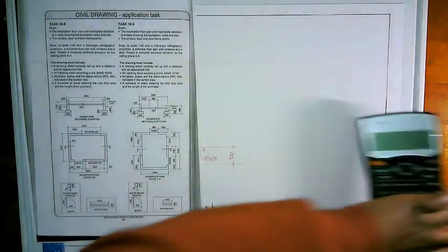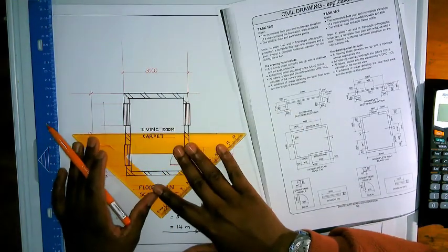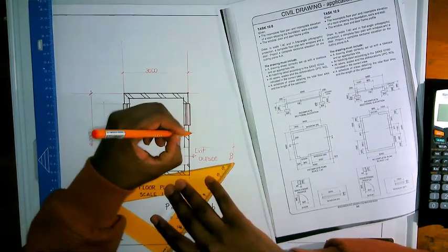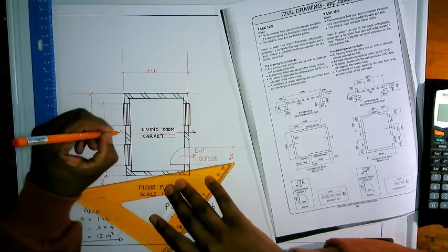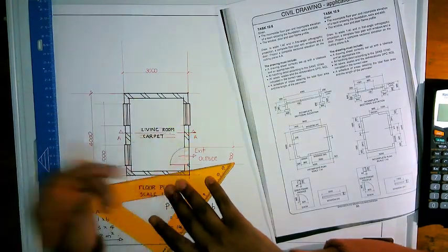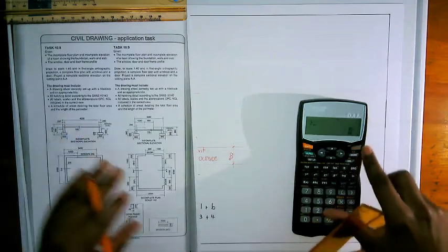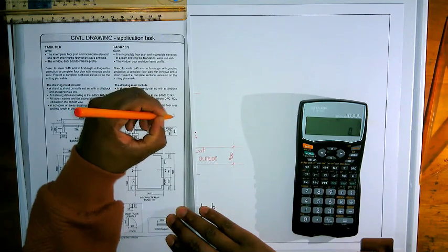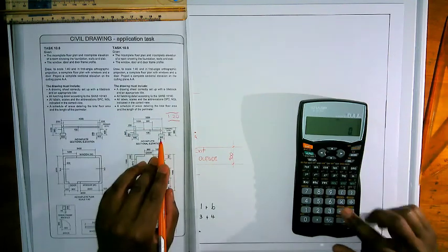Now I want to add the sectional elevation of our drawing, and that must be according to the cutting plane that's provided. So firstly, draw the cutting plane and copy it as it is. You'll see that the triangle is on the line or on that cutting plane and it's labeled. Then you need to use your scale to draw it correctly. Now, typically, sectional elevations are at a scale of 1:20.